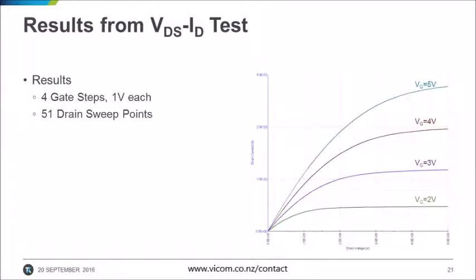This is what the result of the previous test looks like. Notice that we have 4 plots on our graph, and each one corresponds to a different gate source voltage. This image shows very well the 3 phases of FET operation, as well as giving us valuable insight into using it in our own designs. I took this plot using Clarius software and a Keithley 4200A with 4 SMUs as configured 2 slides ago.